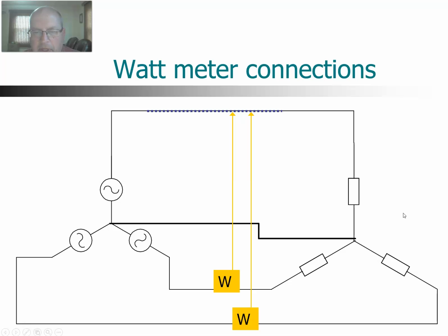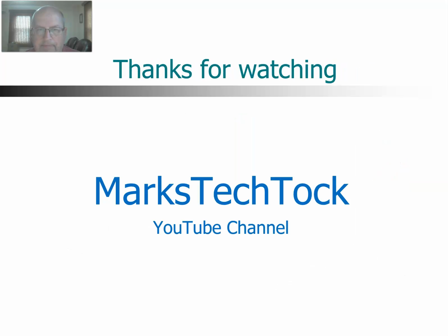And in reality, what they will do is they'll take both of those meters and put them in the same case, and they'll add them together internally so that the meter reader doesn't have to do the addition and potentially make a mistake there. They actually have the instruments all built into 1 meter. All right, so essentially that 1 meter is really 2 wattmeters in the same case, and that is reading the total power for your three-phase load.